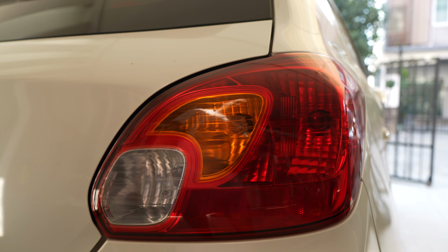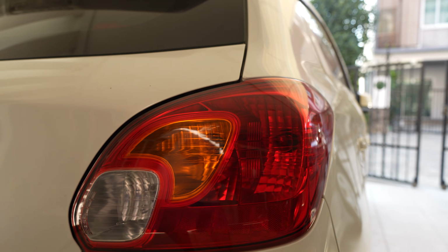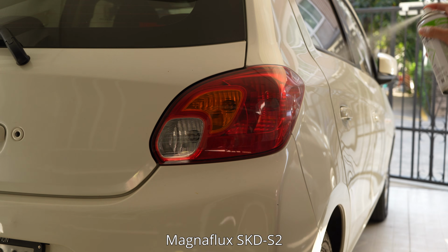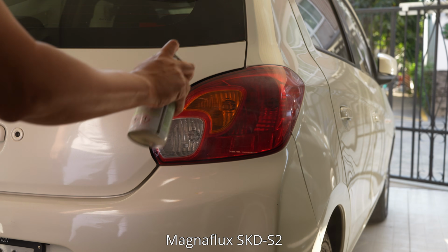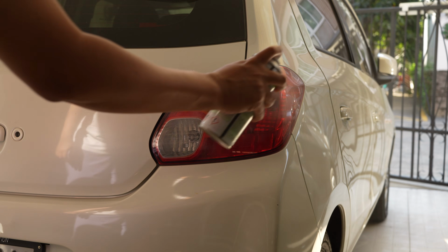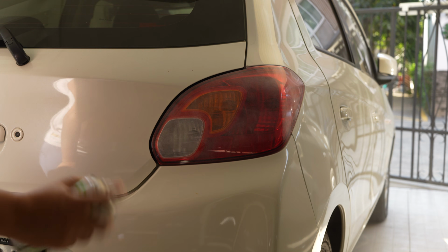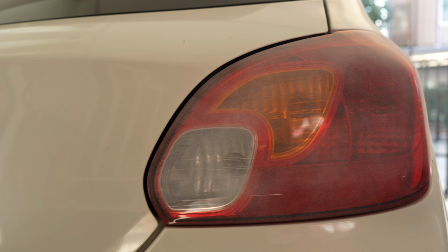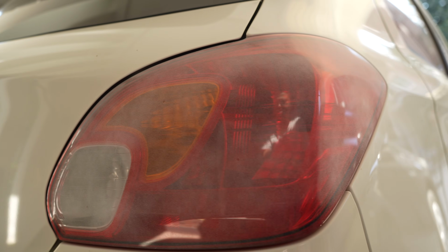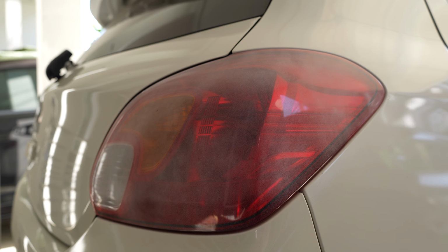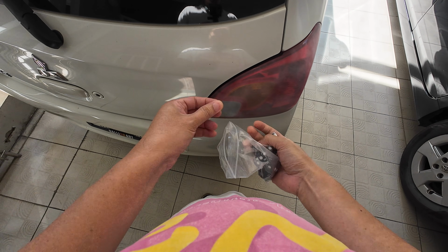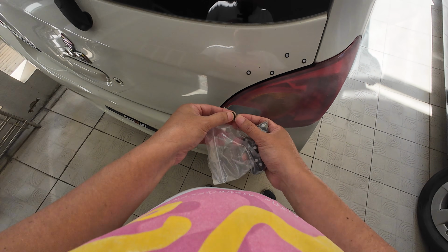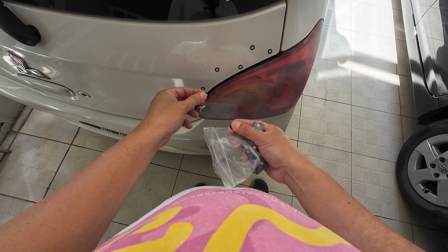Because the surface that I'm going to 3D scan is translucent, I need to use the spray to cover up the surface before starting the 3D scan. So now we have a nice thin coat of the spray. It should be good enough for making a 3D scan. Next I will apply markers on the surface. So I'm going to put the magnetic markers along the edges. And I'm going to put the sticker markers inside of the tail light.